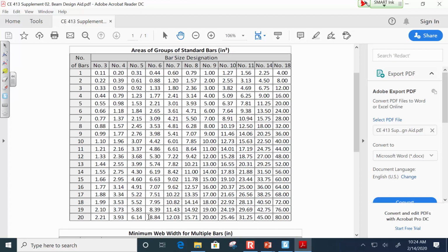All right. What about, maybe we ought to go a little smaller. What about number 4s? How many number 4s would we need? 11. No, hold on. 9 is 1.77. 10 is 1.96. We need 10, right? Good. So yeah, 1.77, 1.96. I know that can be a little weird to see.